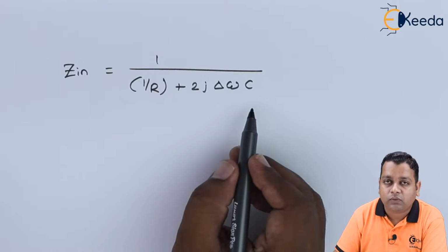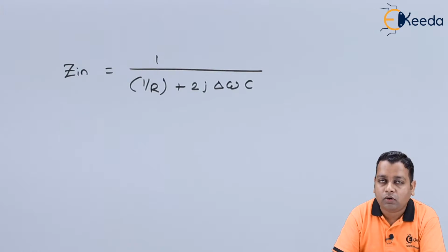So this is the equation for the second topic. We have obtained the parallel resonant circuitry with the parallel connection of RLC, the lumped elements here. Hence I can say that a section of transmission line which is shorted at the end and having the length of lambda by 4 is working as the parallel resonant circuitry.